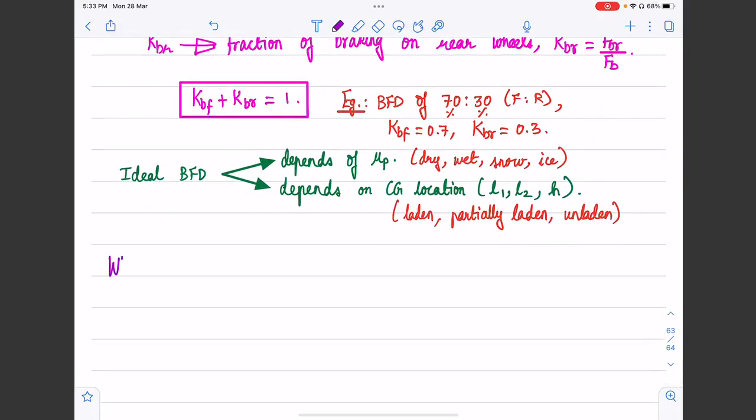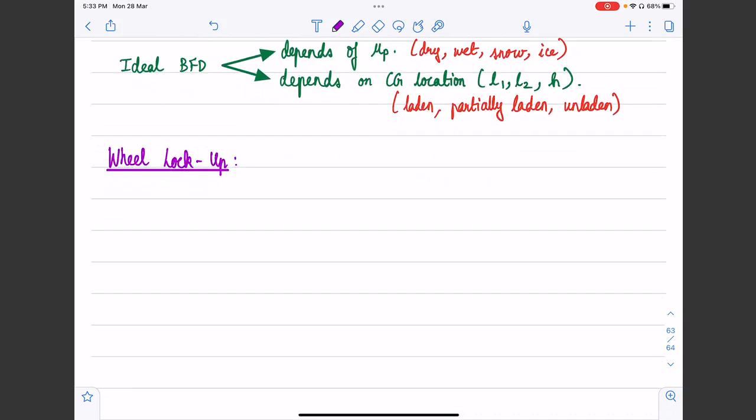All right. So what we are essentially going to ask ourselves in this discussion is, can we get simple expressions which provide us bounds on the vehicle deceleration at which, let's say, front wheels or the rear wheels will lock? And when will a wheel lock? Because the wheel will lock when we are essentially trying to get more braking force output from a wheel than what the tire road interface can sustain. So let's look at it in some more detail.